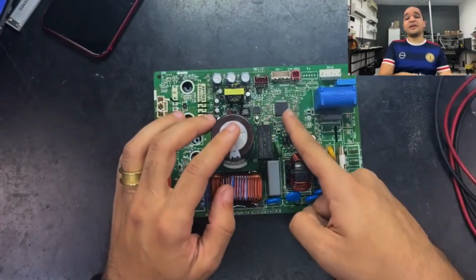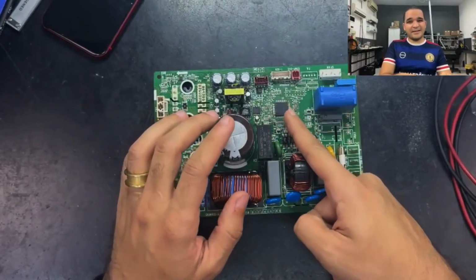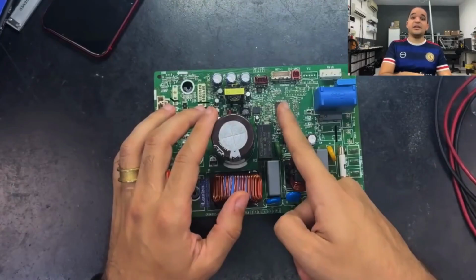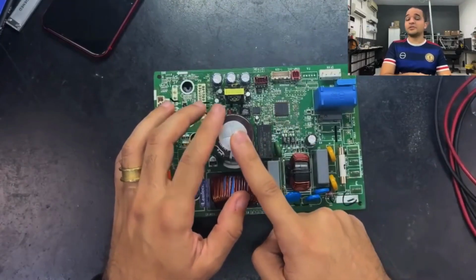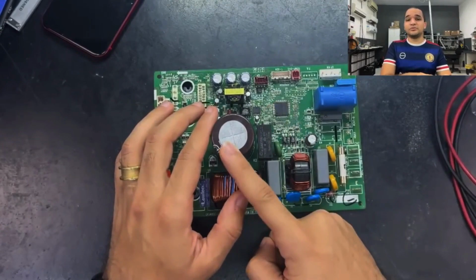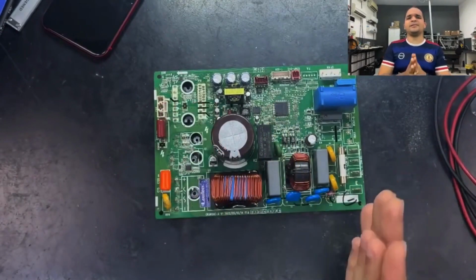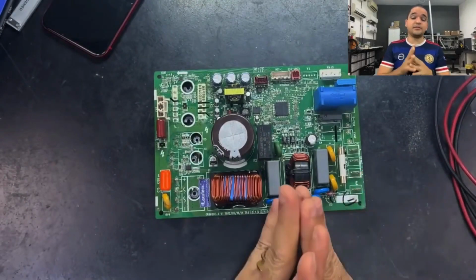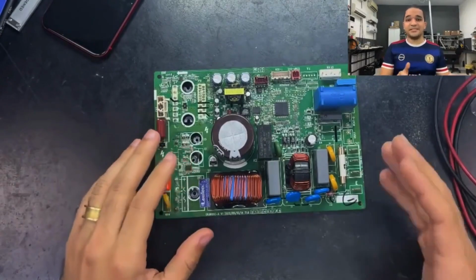And at 310V, this microcontroller will read 3.1V. So when it reads 310V, it will know that this capacitor has 310V. If it reads 3V, it will know that this capacitor has 300V. If it reads 2.9V, it will know that this capacitor has 290V, and so on. It wasn't that number, but it's like this. It's not this proportion of times 100. It can be different in proportion, but this is the logic it follows.